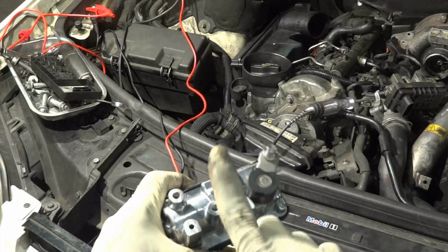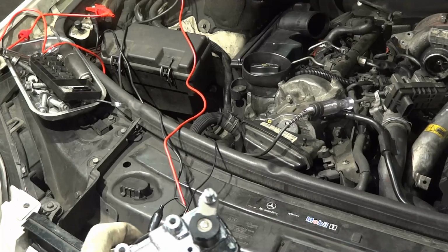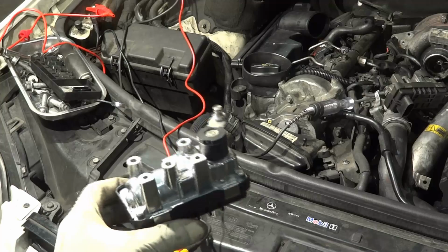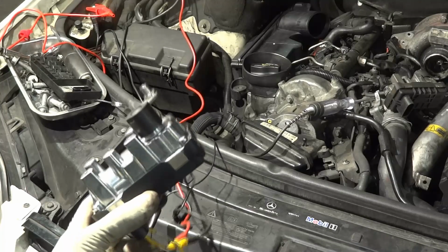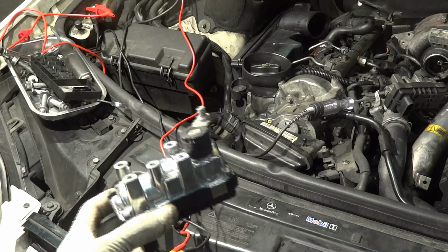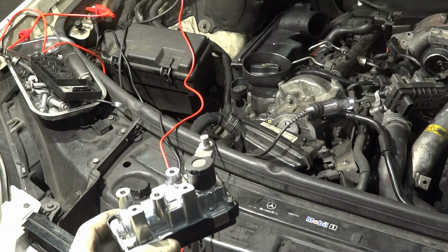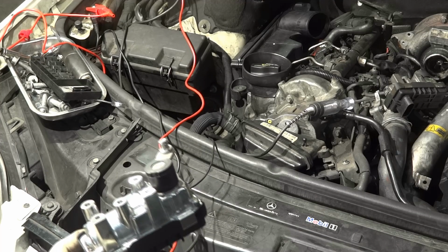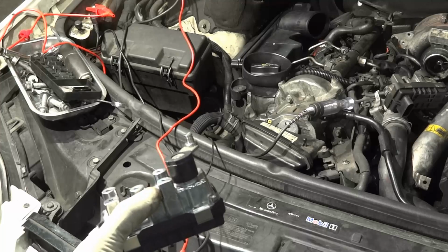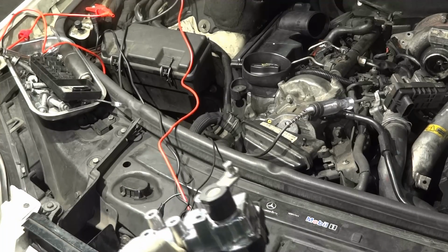Now I'm gonna install the new one on the car. I'm gonna install it, put everything back together, clear the codes, and then we'll go on a test drive and see. But this is the issue, guys. This is what was causing that limp mode concern to come up, because the engine control module could not increase the boost on the engine. So the turbo couldn't spin any faster because of this faulty actuator. So let's install this, and then I'll bring you guys back up.